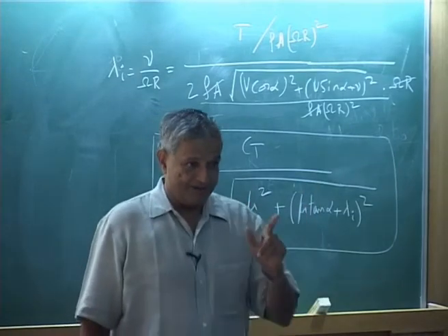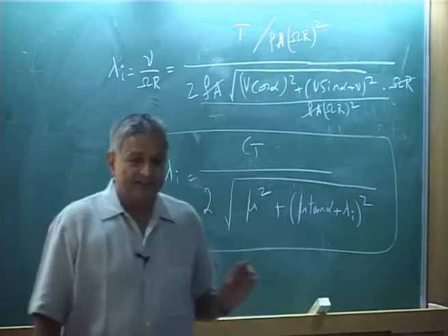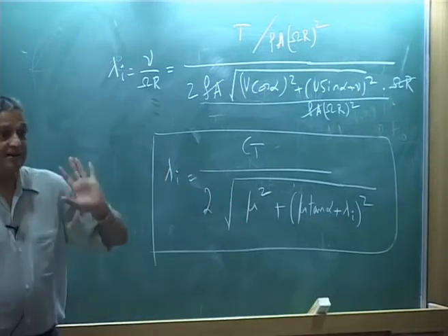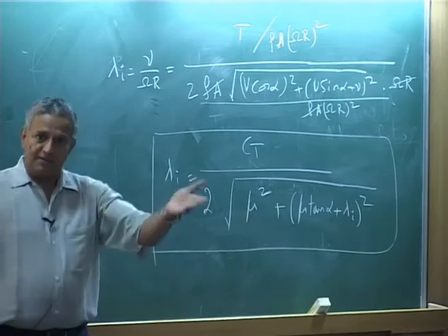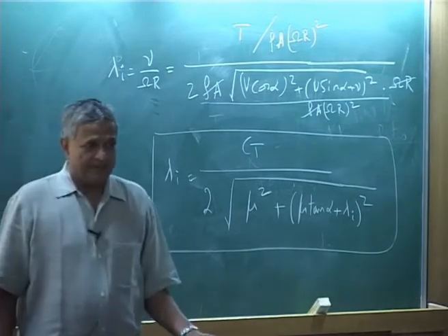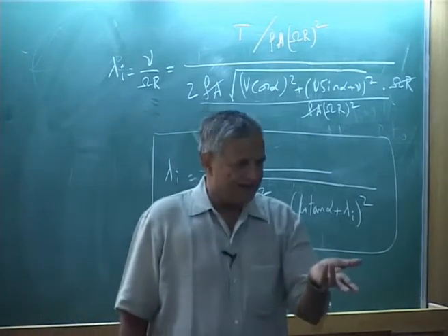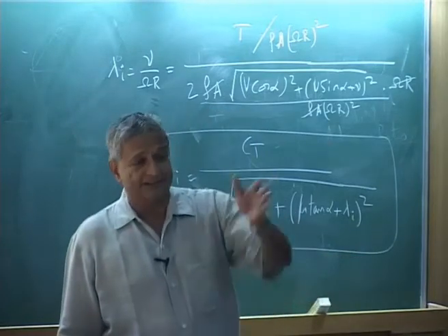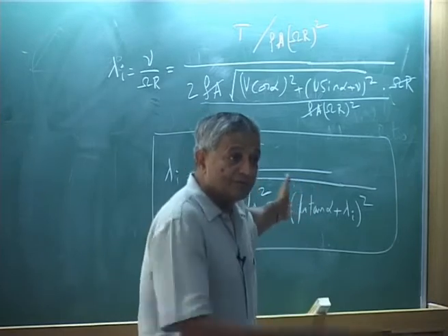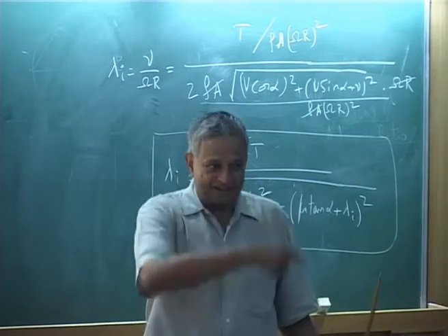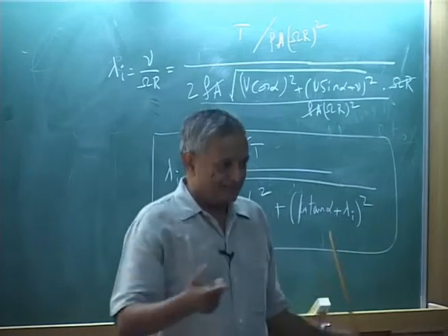Please understand, loosely forward speed by tip speed, because you are neglecting that cosine alpha, but precise definition requires V cosine alpha over omega r. But normally alpha is a very small angle, so it does not matter, you take it as forward speed by omega r. Now, this is the mu which I mentioned earlier in getting the reverse flow diagram, it is the same mu.